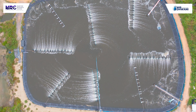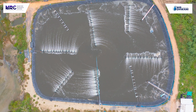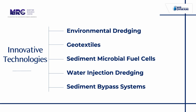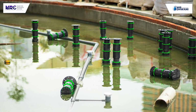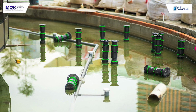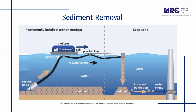Then there are sediment traps and basins, which are settling ponds formed by excavation and an embankment that can intercept and retain sediment-laden runoff from a particular site for a sufficient period of time to allow the majority of the sediment to settle down. Proper use of these structures can greatly reduce the sediment transport, and if properly designed, installed and maintained, sediment removal efficiency of 80% or greater can be achieved, but again it depends on the various soil particle types and the other sediment characteristics.